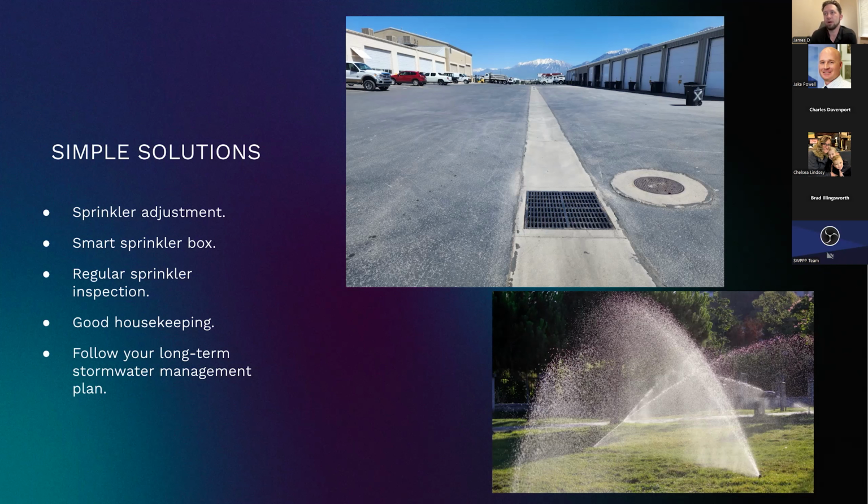And over time, for instance, the underground chambers, the R tanks, kind of the first underground chambers, we had those installed in an area and had them dug up after years and years to inspect how much sediment or leaves are getting into the system. And that helped us improve our design to recommend to developers and keep in our construction standard, and also involved adding an inspection port and a few other things that helped with these long-term stormwater management plan maintenance.